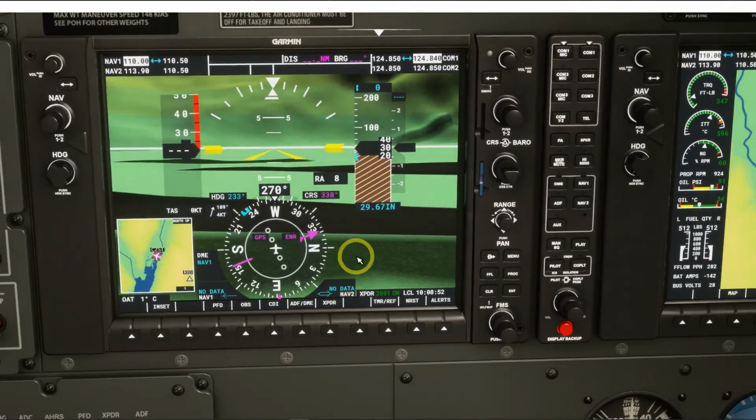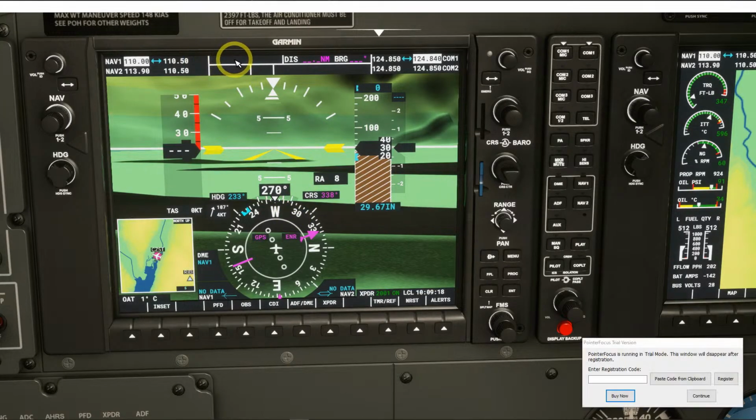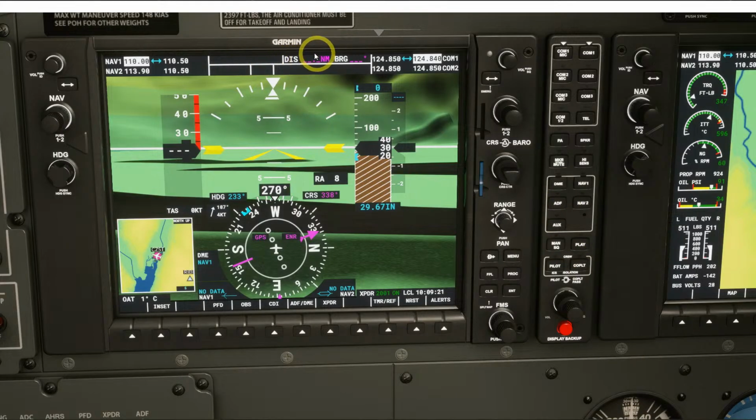So there you go. Of course, at this point everyone or most people know that this would be the altitude that you are at right now. On the left hand side there will be the speed. On the top here, this information here will give you the distance that you are from the next VOR navigation point, or if you are going GPS direct, will show here the origin, the destination, and then the distance that you are, and the track that you're going to be at. And that's about it for the bottom section and the information on the panel here.